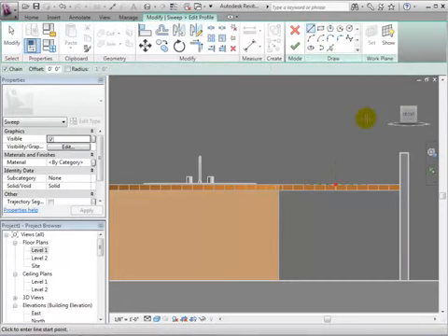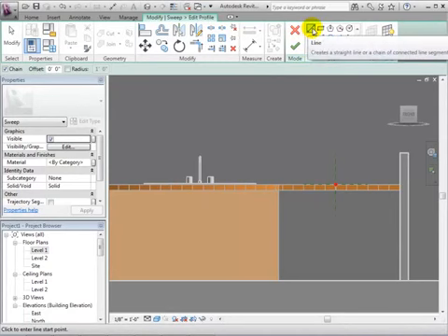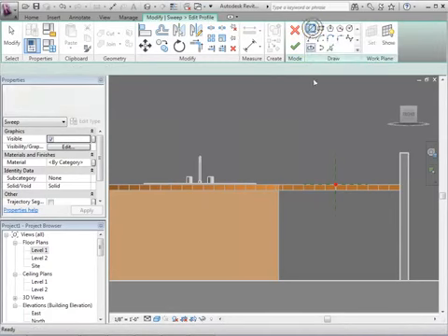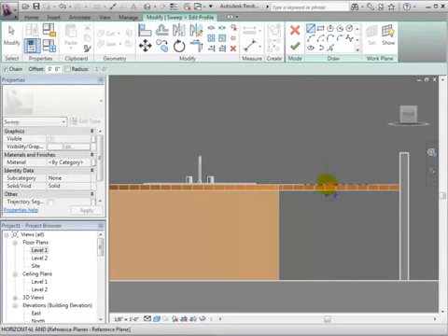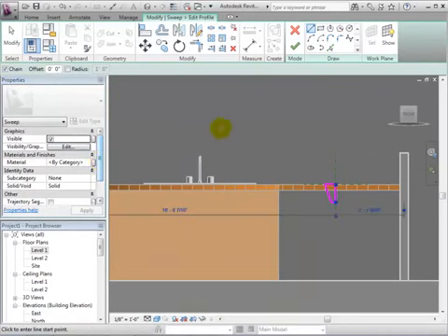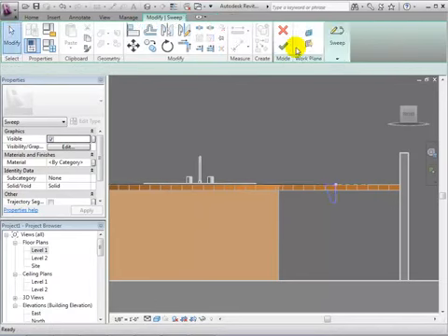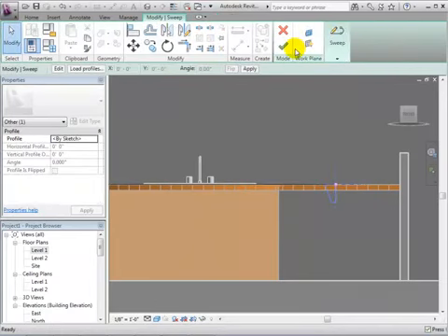This opens all of our drawing tools, and using the drawing tools, we can sketch a profile that will be swept along the chosen path. After making a closed loop sketch, we can change the sweep properties, such as giving it a material, and when finished, select the green check mark. Since we have now selected a path and drawn the sweep profile, we can select the next green check mark to complete the sweep.